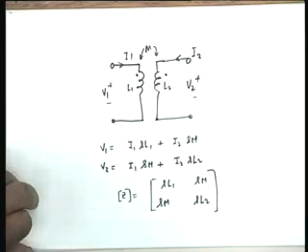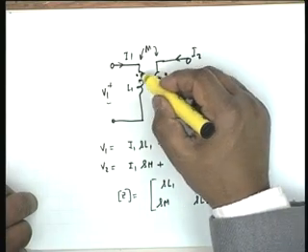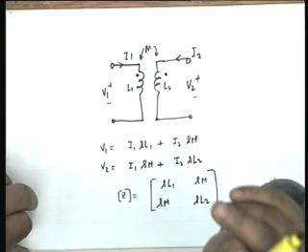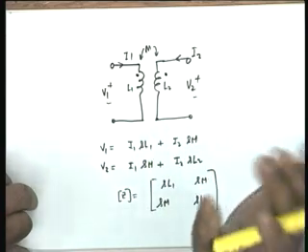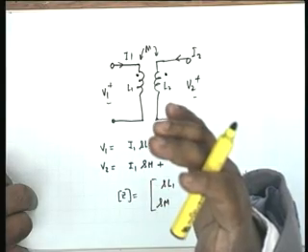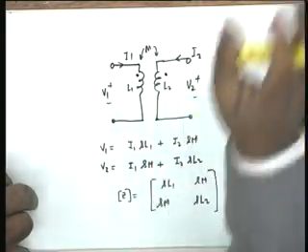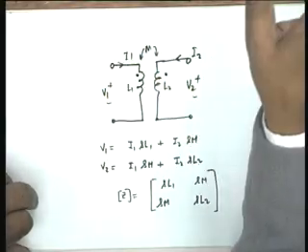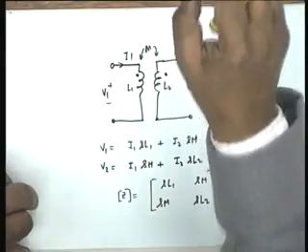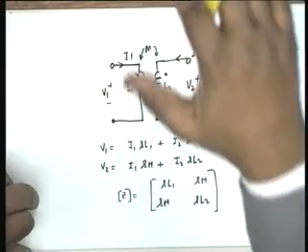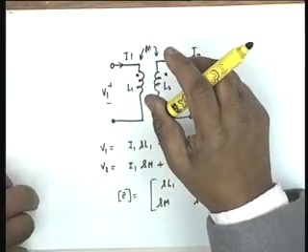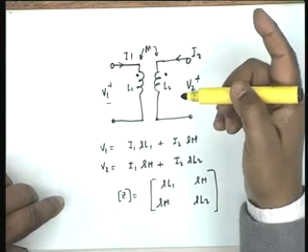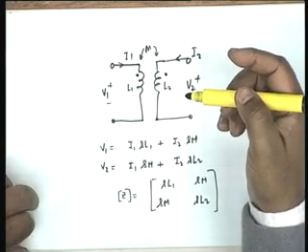Non-ideal in the sense, oh, that reminds me, what is an ideal transformer? Why is it called non-ideal? The L values are not tending to infinity. Correct. If K is equal to 1 and the circuit is lossless, no resistances, it is called a perfect transformer. Idealness is above perfection. Idealness implies that both L1 and L2 tend to infinity such that their ratio is finite. This is the definition of an ideal transformer.